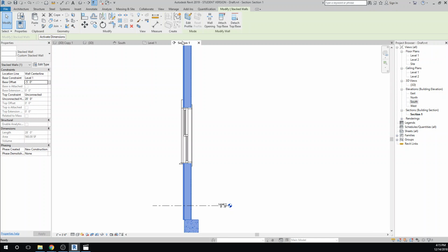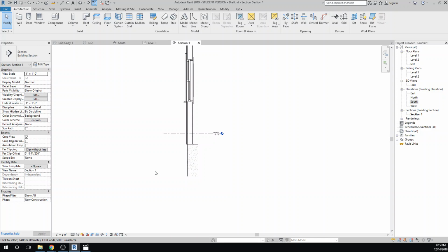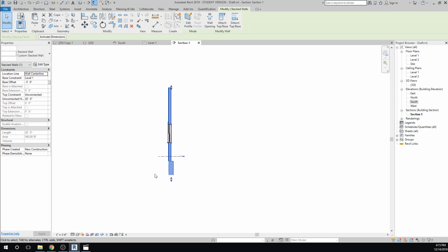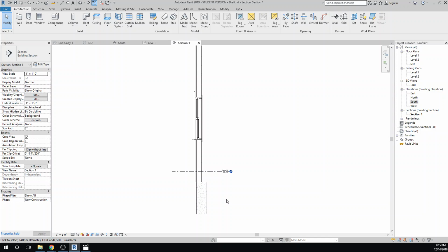So I'm going to click to the section, and now we have our side view. We have our foundation. It looks like we're cropping a little bit. Oops, I didn't mean to do that. I thought that was the crop line. I'm not exactly sure what that element is for doing adjustments. I think that's just the wall height itself, so I'm going to undo that a couple of times till we're back to our wall setting. That was just a wall height adjustment. Excuse my confusion there. So anyway, we have level 1 now. That'll be the first floor entry. We're going to create a floor there.